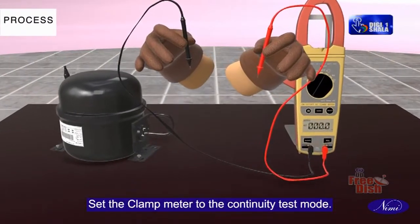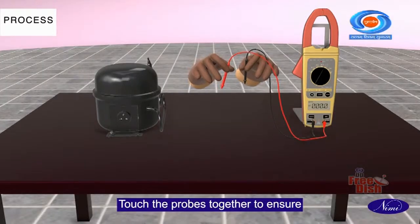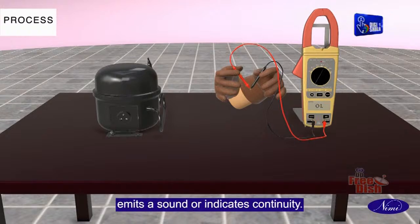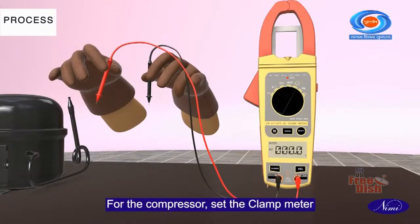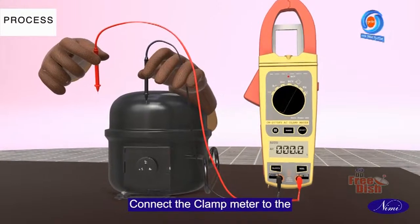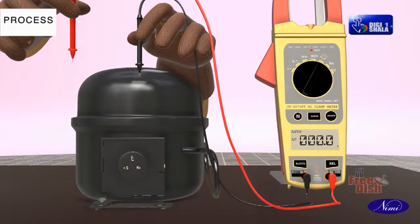Set the clamp meter to the continuity test mode. Touch the probes together to ensure the clamp meter is functioning and emits a sound or indicates continuity. Compressor inspection. For the compressor, set the clamp meter to measure resistance. Connect the clamp meter to the compressor terminal and check for continuity.